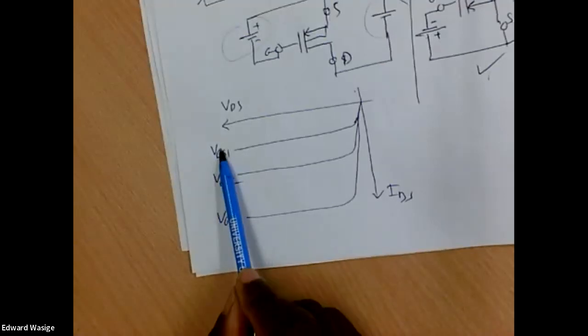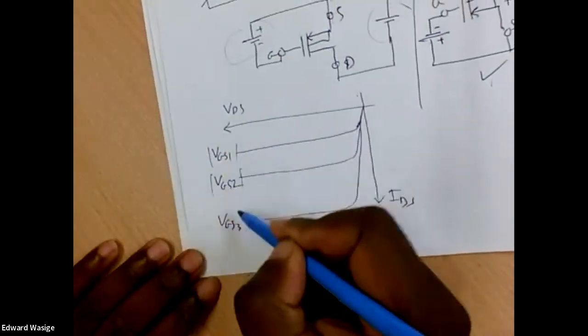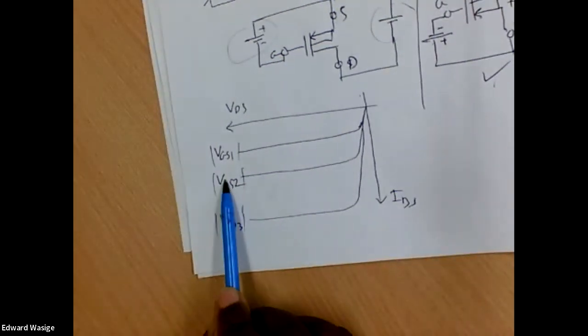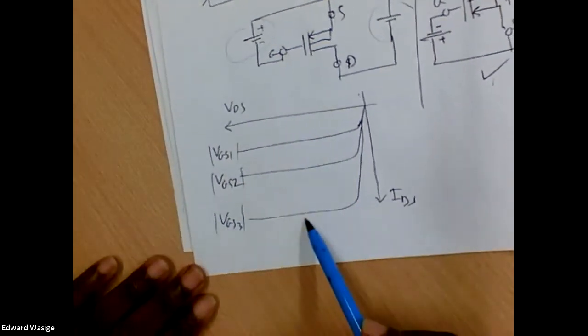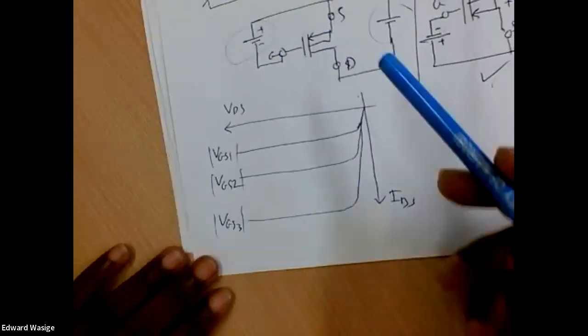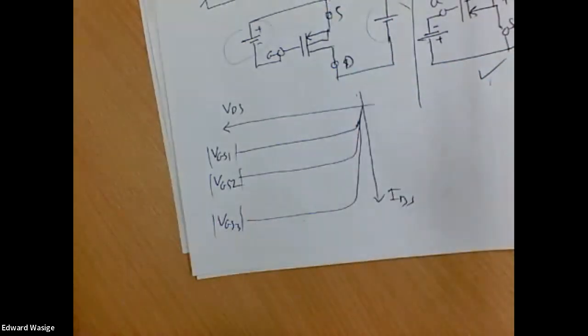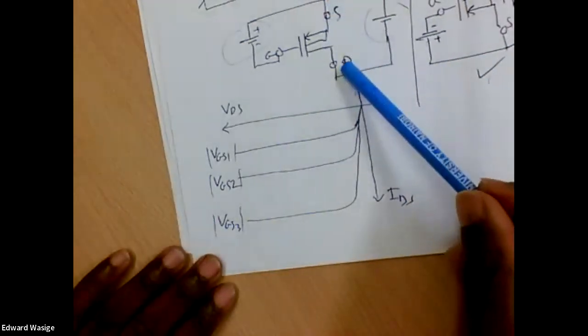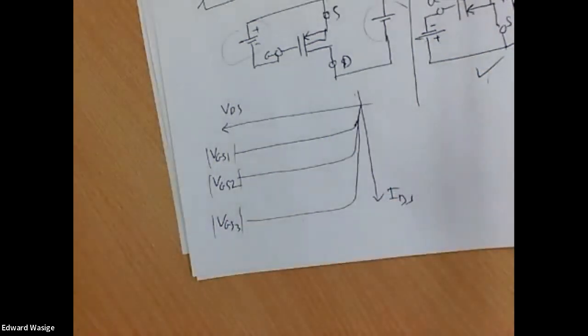So this is some more negative potential to that. In terms of magnitudes, probably better to write them like that. So this is a more negative potential, you have more current flowing, but it flows in the opposite direction to that of an NMOS device. But often, like in an inverter, you're probably looking at the inverter in your digital VLSI part. These two devices are connected in series. So that's why, even though the currents seem to be flowing in the opposite direction, by flipping this device upside down, we get all the currents flowing in the same direction.